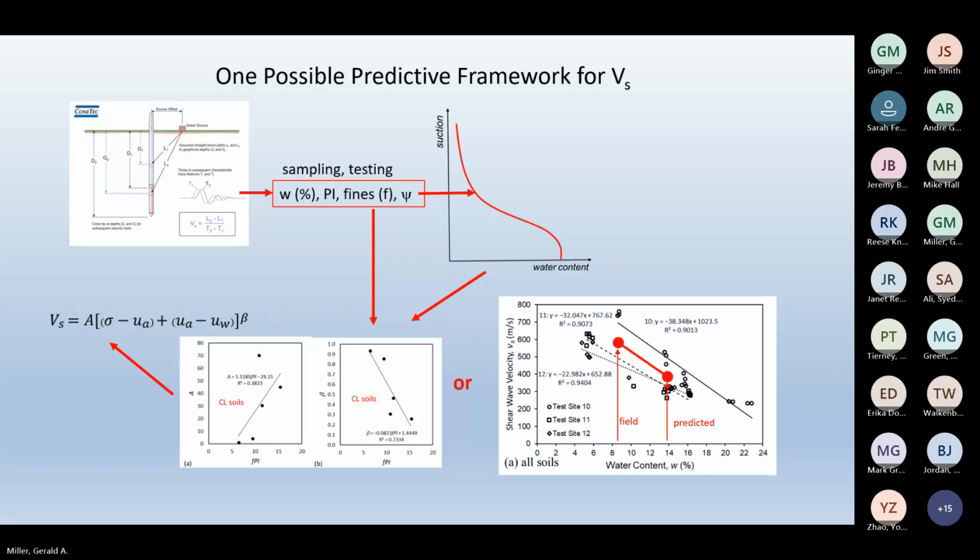And then, if you can, do more Atterberg limits, do more percent passing 200 tests. And if you have the capability, measure total suction. Any additional data is going to help you get a handle on this problem. I know some labs may only do Atterberg limits, 1 or 2 in each of the upper layers or whatever it is, some more, some less. The more you do, the better information you're going to have to predict changes due to wetting.